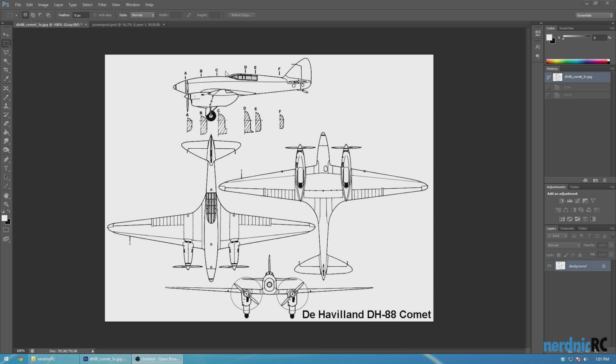The other really important part that isn't necessarily included in a lot of images is the sections here. So we see A, B, C, D, E, F, and then a marker here. This tells us the fuselage shape. So this is key, because just looking at an image without these pieces, it's really hard to know how to design your formers to get the right shape.